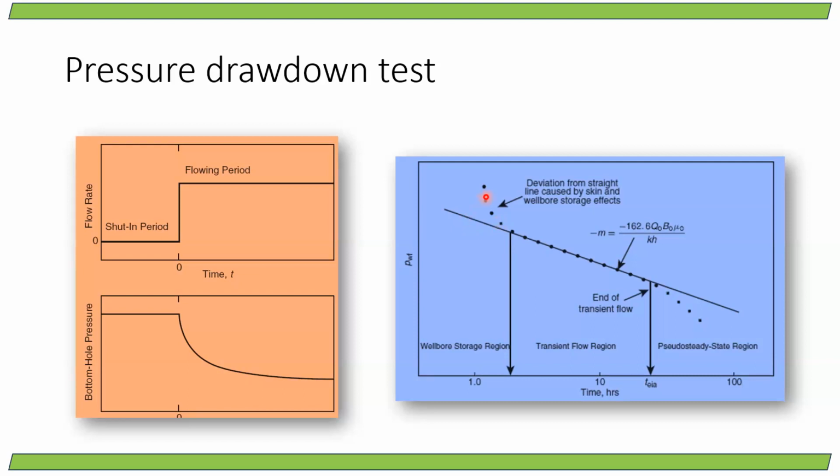That represents you are getting more oil than is required, which shows that something more is coming with the oil. What is that additional amount? It is nothing but the workover chemicals that were present in the annulus inside the wellbore. That will mix with your oil and start producing initially for some time. So the wellbore damage effect will last for some time. After that, it will fade out.